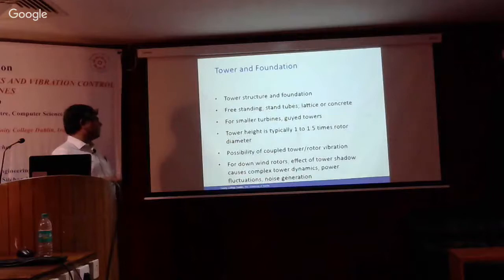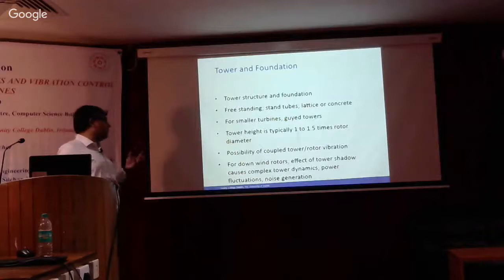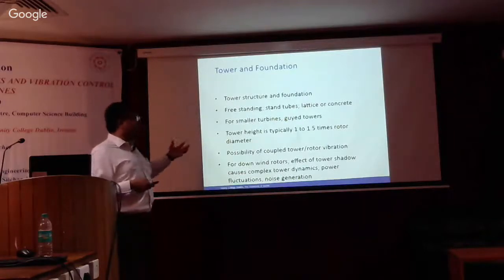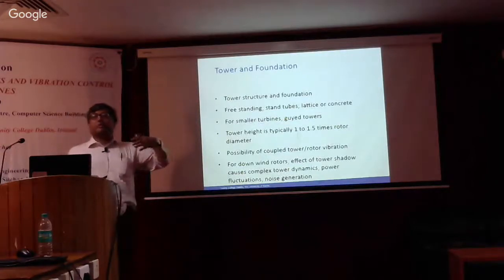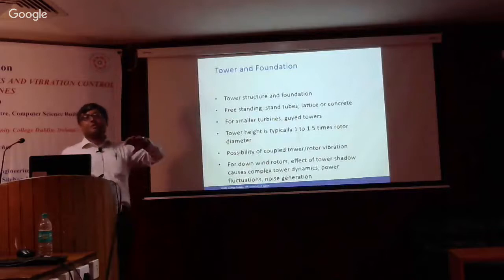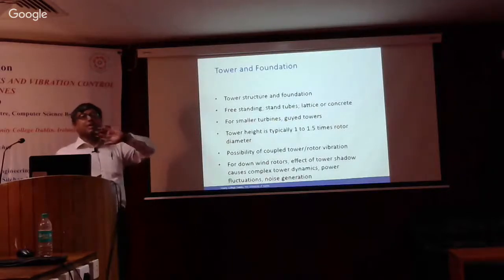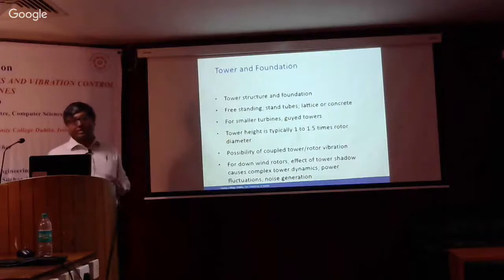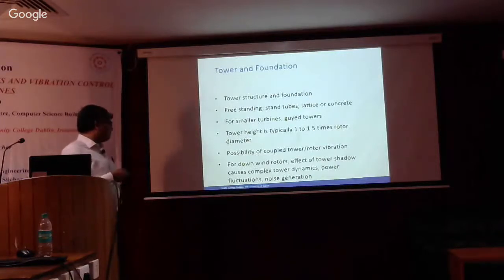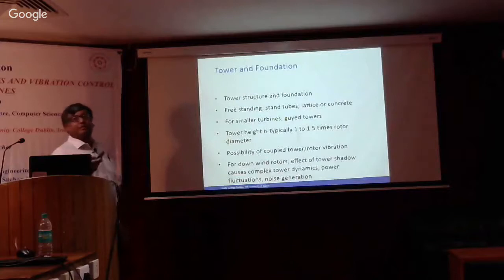The possibility of tower-rotor vibration getting coupled, which we have explained in theory and in concept, we'll see how this coupling happens when we derive some equations, maybe not tomorrow, but the day after, when we look into the structural dynamics modeling, how the gyroscopic stiffening gets connected, how the damping actually gets affected. So that's where you see that because of this coupling of the mass, we get a negative damping. And the velocity terms come because of the coupling. So not just an inertial coupling, but there's also coupling in the velocity terms as well.